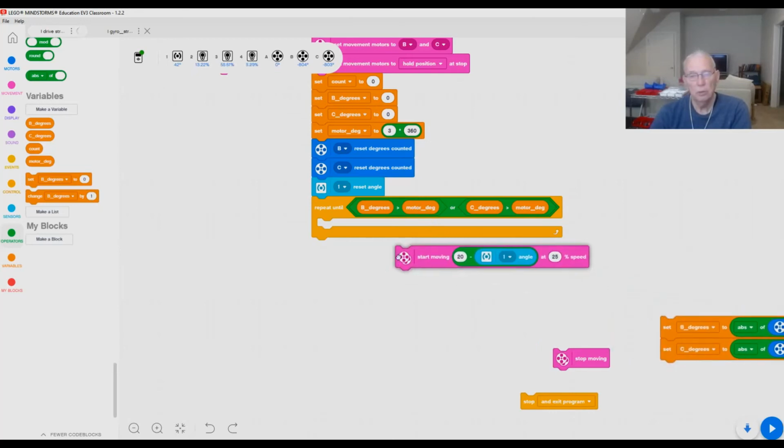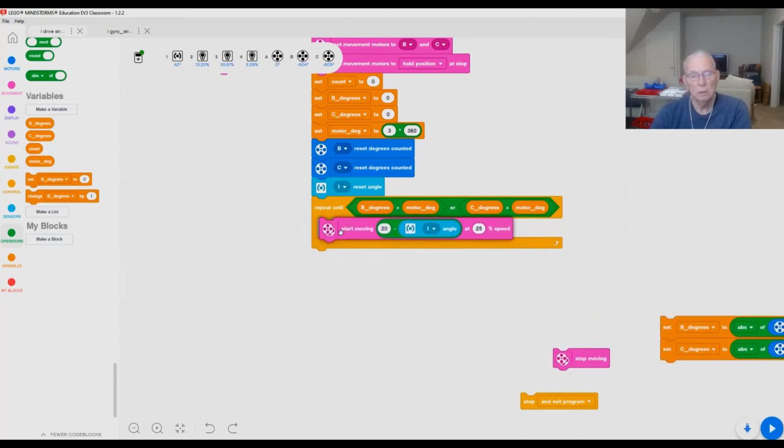So now I start the motor moving in the loop, and that should be 0. And I want it to go straight ahead, which I've already set this angle to 0. So if this number is negative, then that means the robot is turned a little bit to the left. And if I tell it to move minus that angle, it will turn toward the right until this angle zeroes out. Now, after I start it moving, then I want to measure